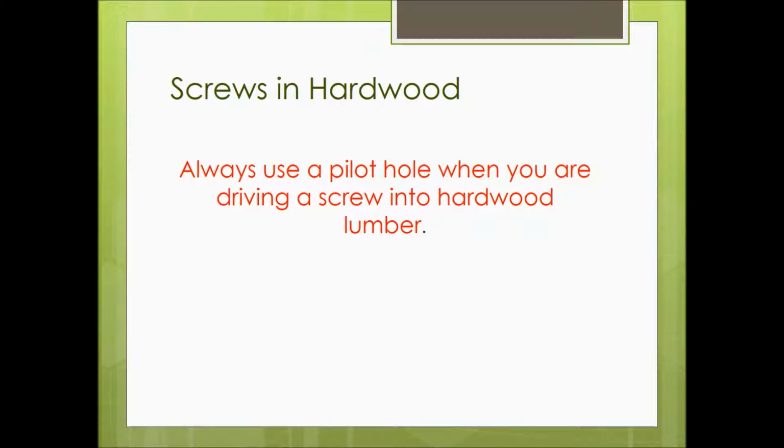Anytime you are putting a screw into hardwood, and when I'm talking hardwood, I'm talking about your maples, walnuts, oaks, hickory, that type of thing, you're going to have to put a pilot hole in it. If you try just driving a screw into it like we do when we're building our Adirondack chairs that are made out of pine, or anything else that we made in pine, you can pretty much just drive a screw right into those without splitting it. But if you try to do that in that more dense wood, which is hardwood, you're going to split it every time. So always use a pilot hole.